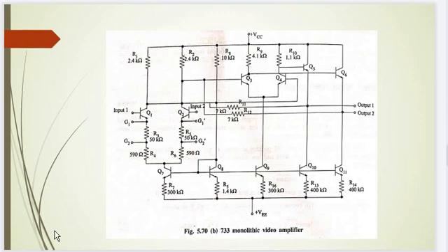The second stage, formed by transistors Q3 and Q4, is driven by the balanced output available from the first stage. The transistor Q9 provides the current sink bias, and the resistors R9 and R10 act as load resistors for the second differential stage. The second stage output drives the two emitter follower stages realized by Q5 and Q6. The transistors Q10 and Q11 act as current sink bias for the emitter followers.